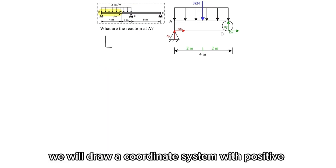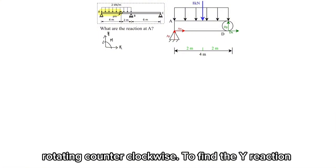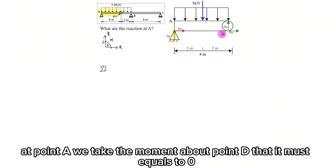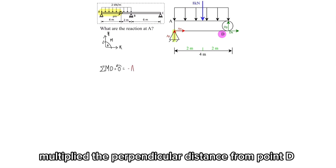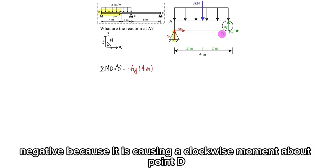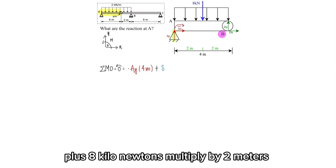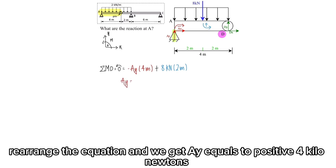We will draw a coordinate system with positive pointing upward and to the right, and positive moments rotating counterclockwise. To find the y reaction at point A, we take the moment about point D that must equal 0, which equals negative AY multiplied by the perpendicular distance from point D, which is 4 meters. Negative because it is causing a clockwise moment about point D, plus 8 kilonewtons multiplied by 2 meters. Positive because it is causing a counterclockwise moment about point D. Rearrange the equation and we get AY equals positive 4 kilonewtons.